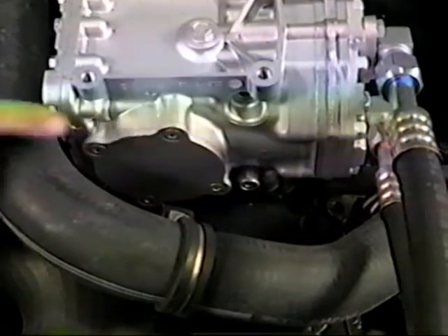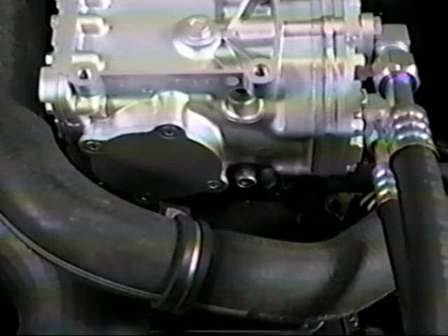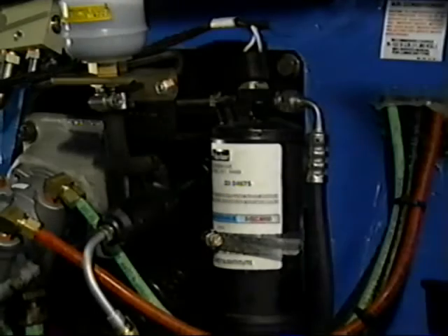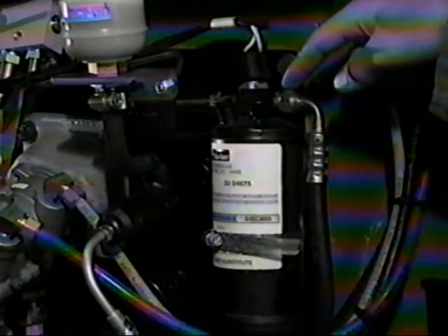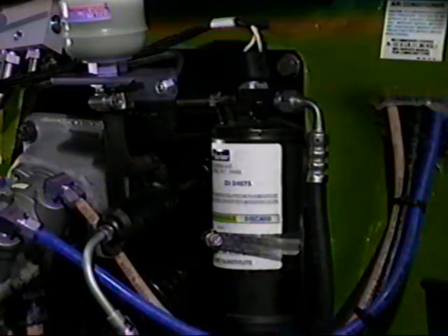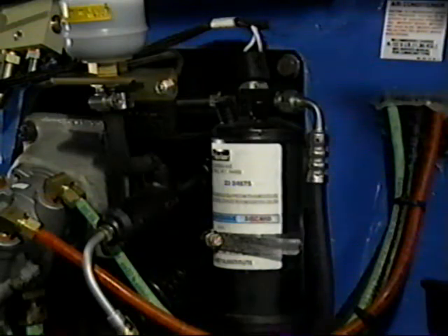A self-sealing high-pressure relief valve is located on the housing of the AC compressor. Note, the crankcase of the 2-piston compressor is pressurized, so the refrigerant charge must be dropped before checking the oil level. The receiver dryer features a male fitting going in and a female fitting coming out. This design is intended to make it more difficult for the unit to be plumbed backwards.